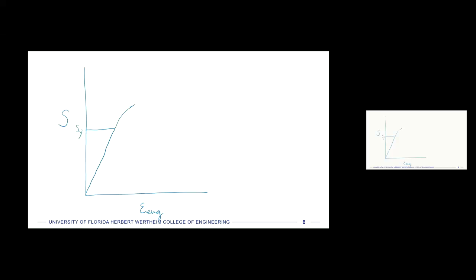And because I've curved it out, if I've stretched it out and now I release the load, it's going to come back a little bit, because at the point where we stretch it to, we have both elastic and plastic deformation happening. So if I release it all the way back to 0 stress, it's going to come back down like this. All the way back to 0 stress, but there's an offset in the strain axis. Another way that you can describe a plot like this, where it doesn't follow itself, is that there's hysteresis. That's the fancy name for the plot doesn't lie on top of itself. There's a change in one condition.